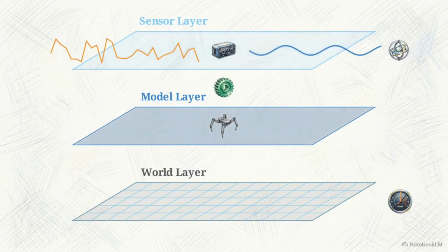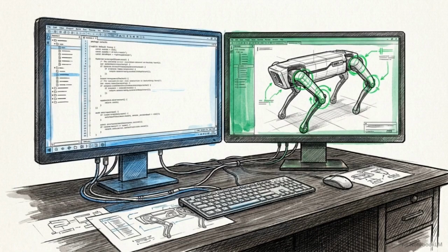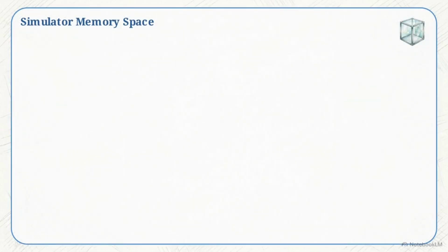To integrate your logic, the C++ code follows a specific life cycle, beginning by inheriting from a parent model plugin class. The first essential block is the load method, which the simulator executes once upon startup. During load, the plugin initiates joint references, allowing the code to directly manipulate the robot's degrees of freedom in memory. While initializing, the script also sets up an event listener.